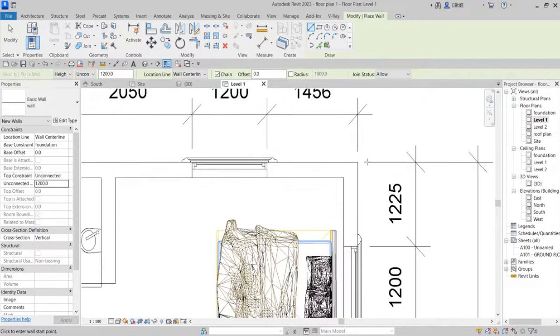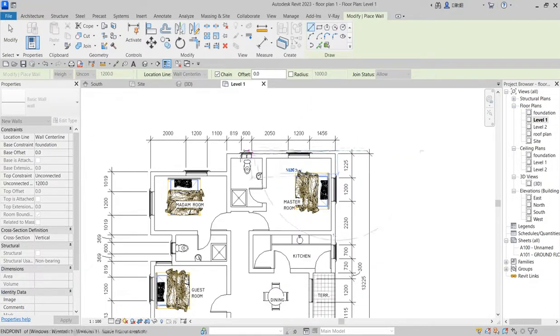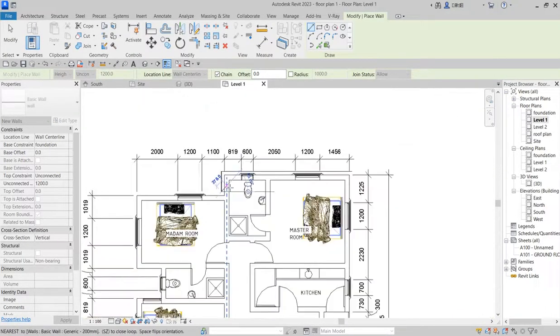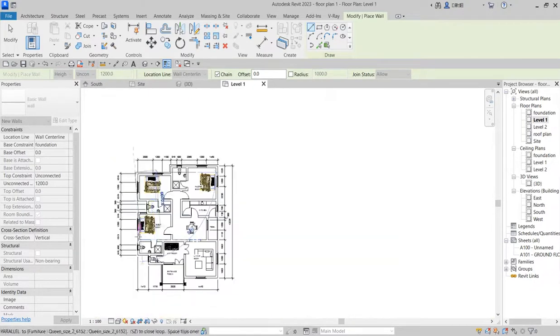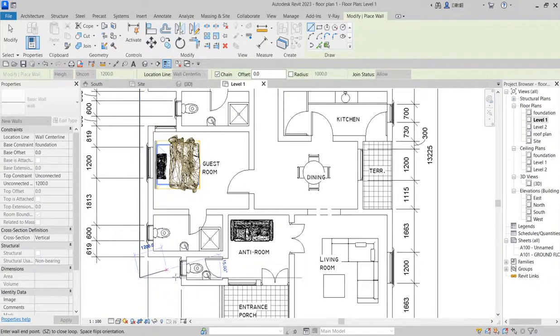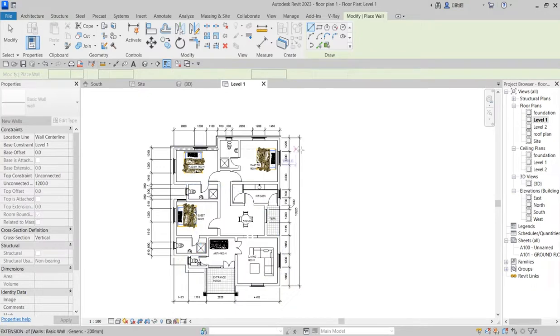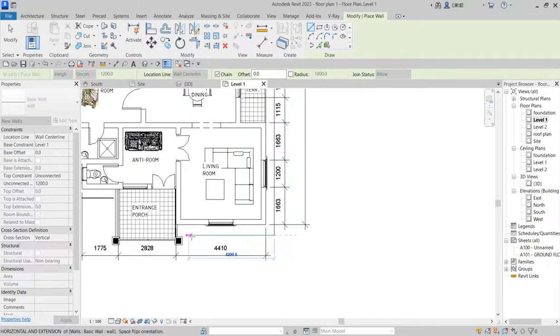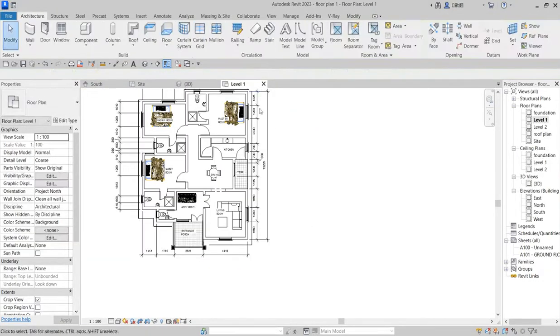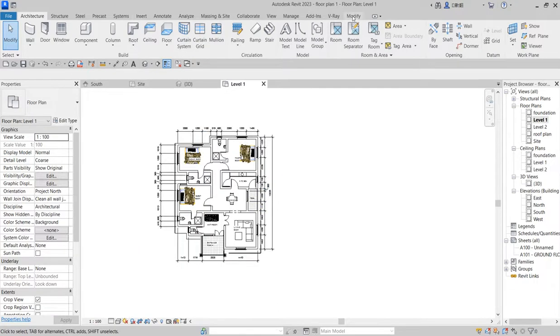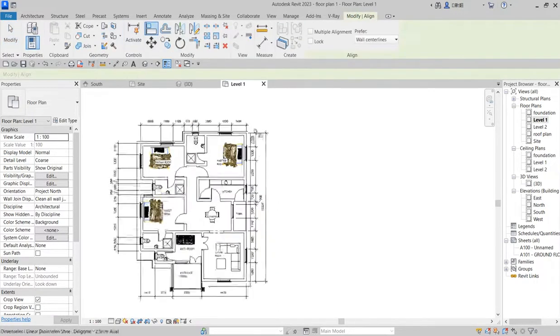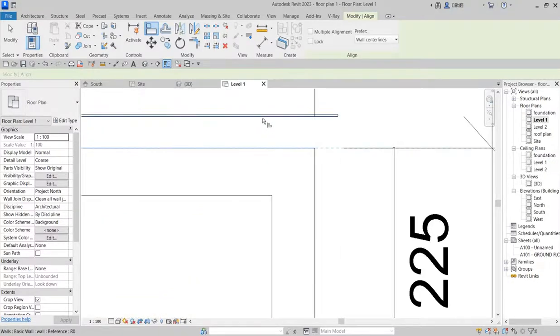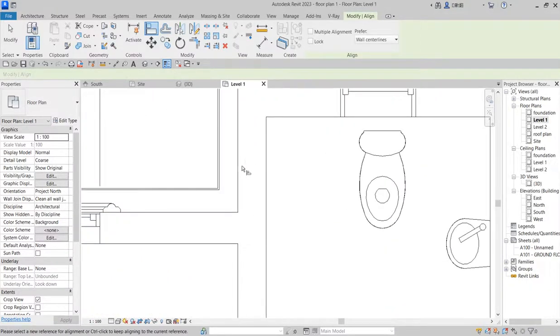So you drag it around, you draw it around like that. Do not use pick line to choose this because the wall might be intersecting, and that will be a lot of confusion when you are doing the editing of this, because you can never say this is the last point of which you are going to stop. So as you've done this, what do you need to do next is to click and say align all those walls to where you want them to be. Use face to click all around.